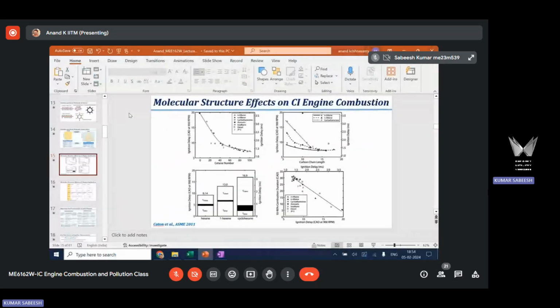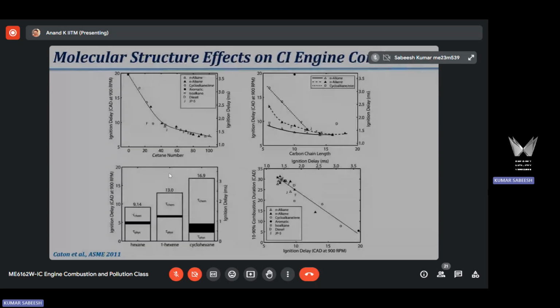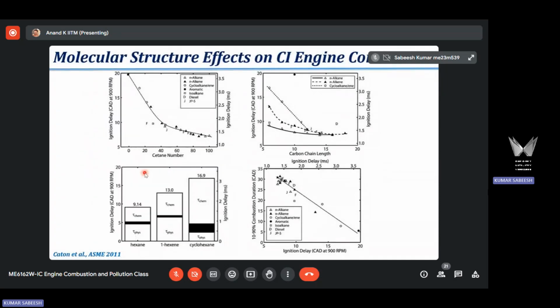So in a diesel engine, we have discussed the ignition delay trend with molecular composition. In an SI engine, a spark ignited engine, technically there is nothing called ignition delay time because you discharge an electric spark. Because of the high thermal energy that you provide, ignition happens almost instantaneously. There is nothing called a delay. Here there is a delay because it's self-ignition. Before self-ignition, there are many processes taking place. We already discussed that, physical delay and chemical delay. This is applicable for a diesel engine or CI engine because of the nature of the ignition event, which is self-ignition.